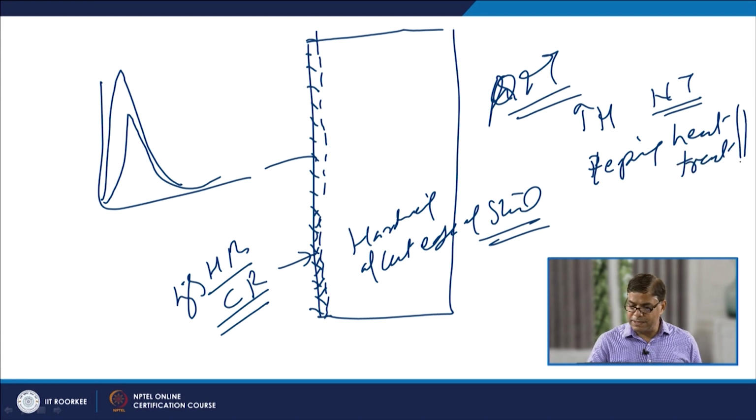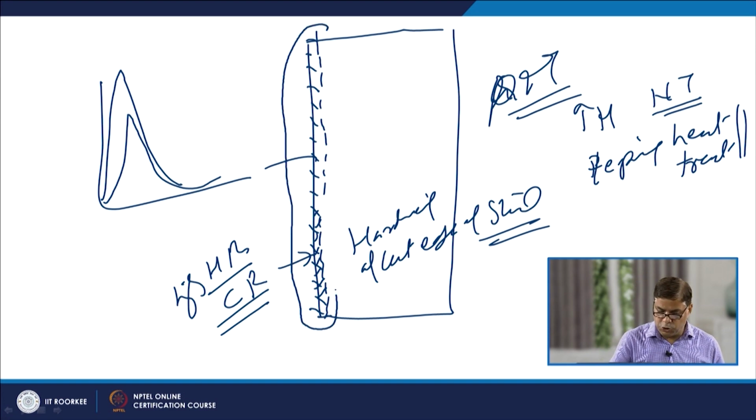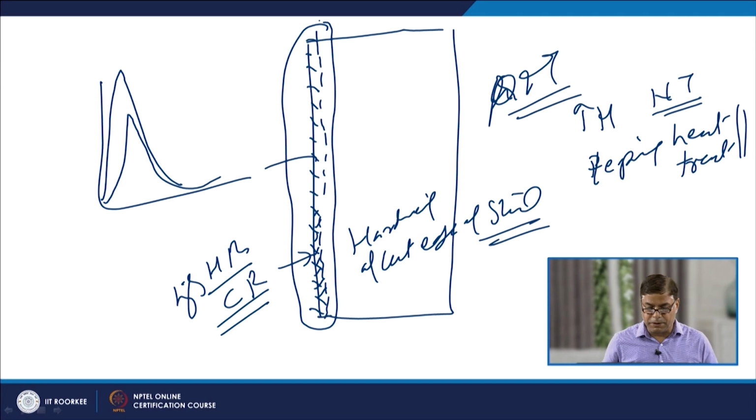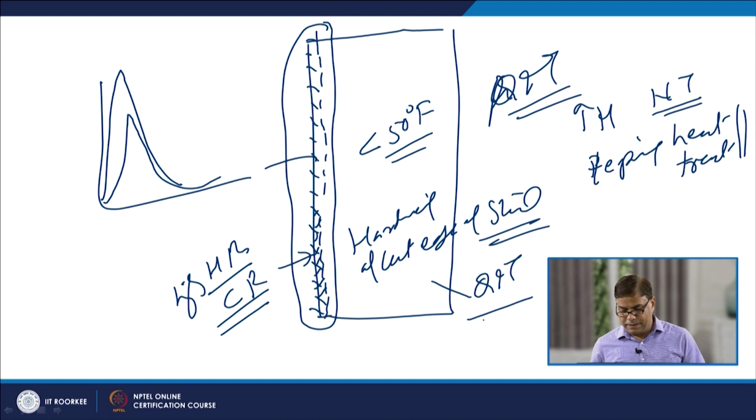And in this case the tempering treatment will be applied to the zone which has been affected by the heat applied during the cutting. So, the tempering of this zone is carried out, and if the entire plate is to be subjected to heat treatment after the cutting, then we use a temperature 50° Fahrenheit less than the QNT tempering temperature, the temperature at which the steel was originally tempered.